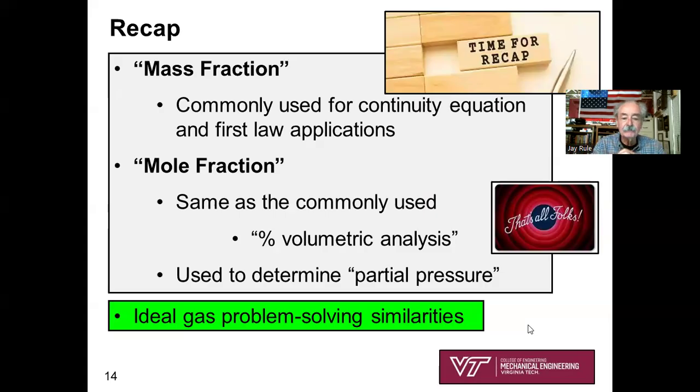Okay, the recap of definitions. A mass fraction is commonly used for continuity equation balancing in mixing problems and the first law. Mass fractions, because remember, mass is conserved, not moles. Mole fraction is the same as the commonly used volumetric analysis. In the working world, when you see the words volumetric analysis, the engineer immediately says, "Oh yeah, that's the molar analysis," or in other words, the mole fractions are given.